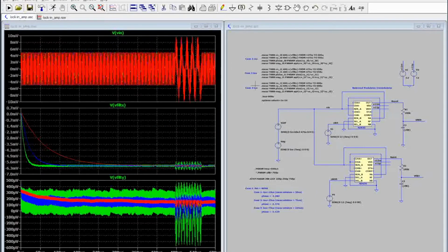So this example shows a 60 kilohertz signal of 5 millivolt amplitude, which is the same as the input signal, but at a much lower frequency value. So it's going to have much less of an effect. And as you can see from the V filter X and V filter Y, the settling at the beginning is the same, but the noise comes in at 475 microseconds in the simulation, and it lasts for about 20 or 30 microseconds.